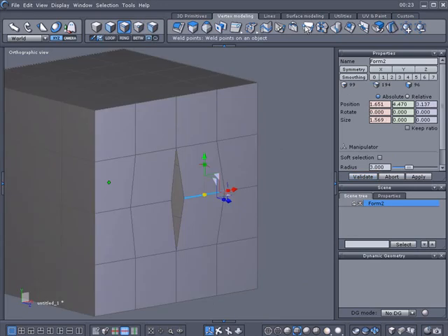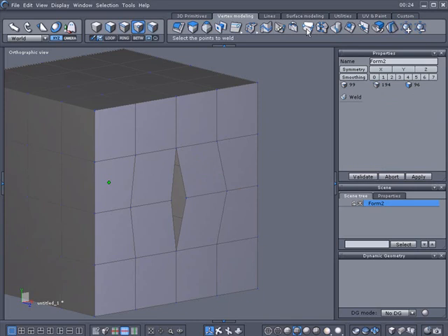We're going to go over a weld point up here, this icon here. And as you can see in this cube here, I got a little tear in it. And I'll just go ahead and select the weld point. And I'll select the first point and the end point by clicking it, and it'll weld it together. I'll Control Z that. And we can also right click, draw marquees, and let go, and it'll weld it.